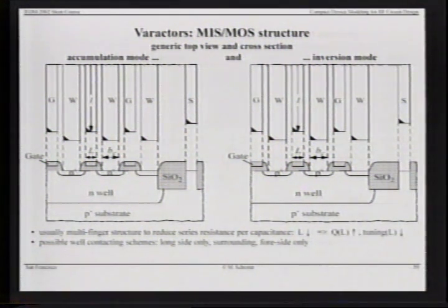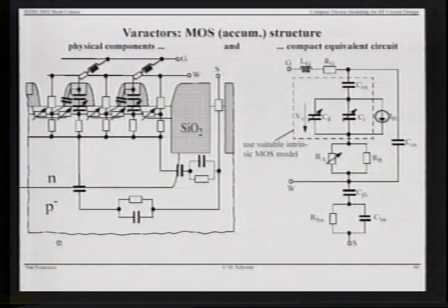It is important to mention here that the MOS models that you usually get in a library cannot be used at those high frequencies as a high-frequency model, because people usually, when they extract parameters for a MOS model, focus on completely different operating ranges, and usually they don't model, for instance, accumulation very well in MOS models, because that's something that is not being used in regular operation for RF CMOS. So there is an additional effort for the foundry to extract parameters specifically for these Varactors.